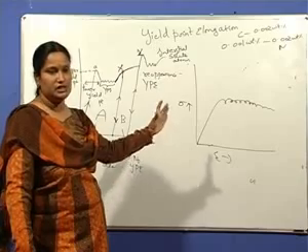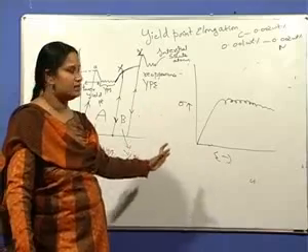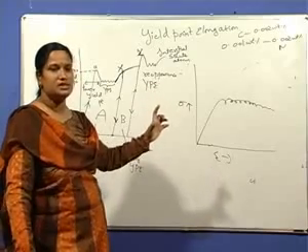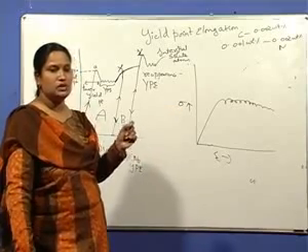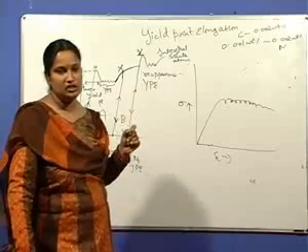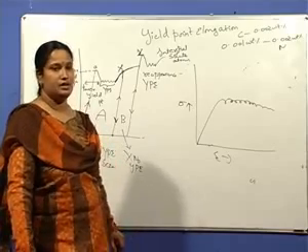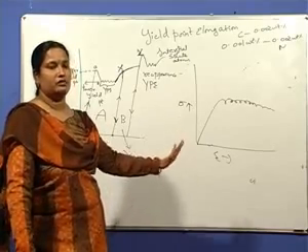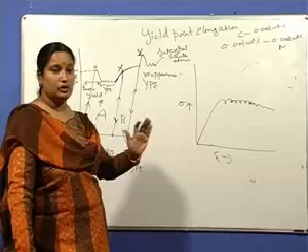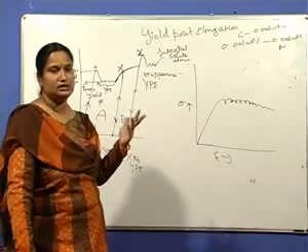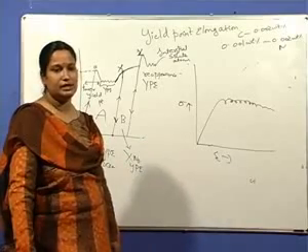And during deformation, if strain aging occurs at temperatures around 200, 300 degrees, it forms very fine serrations in the stress strain curve. The reason for this is the solute atoms diffuse rapidly to the dislocation cores because of slightly higher temperatures. But beyond 400, this effect will cease to operate, because at higher temperatures the thermal vibration of the atoms is more intense.